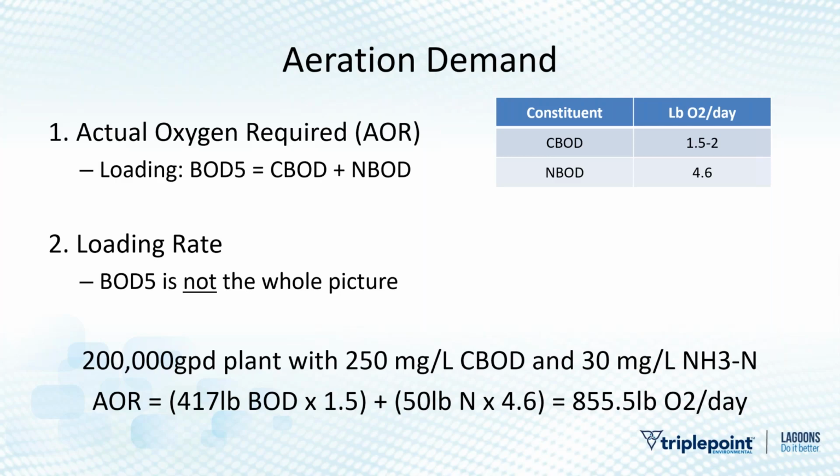It goes out in the ocean, becomes fish river, but they didn't care what the oxygen demand was at that point. But there still is an oxygen demand beyond BOD5. Yeah, BOD5 is not the entire picture, and things continue to break down. And some things break down for a really long time, and we got to provide the air for that.